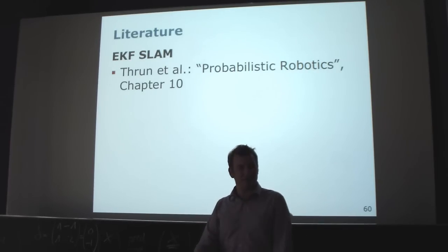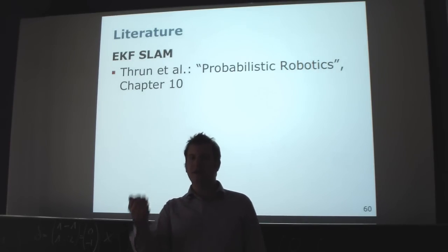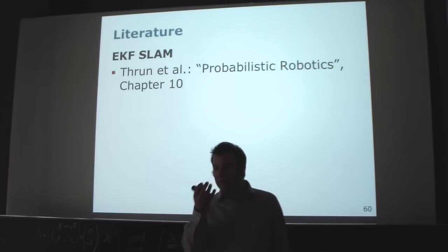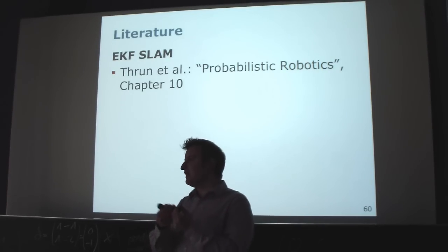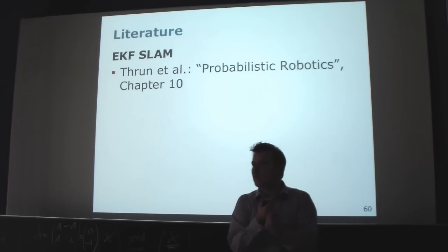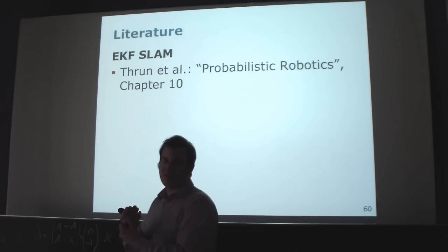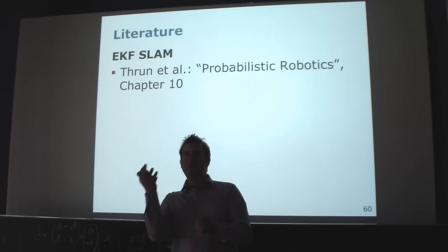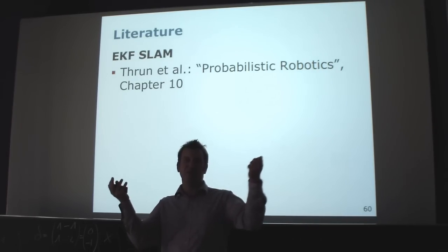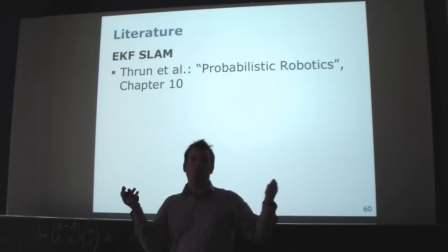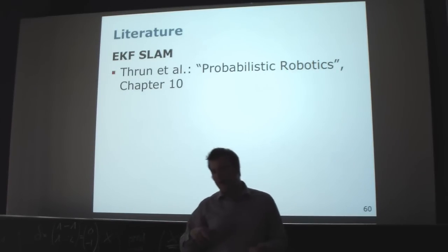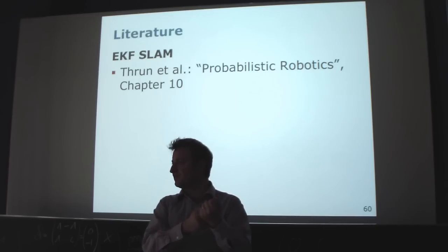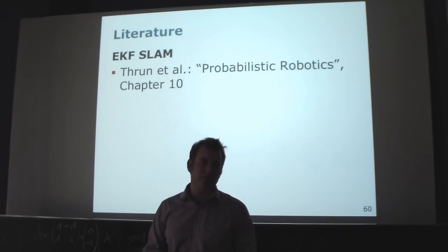So you have some gating function which tells you whether to create a new landmark or use an old one. You may create a new landmark, and later on have two landmarks at exactly the same location, which may indicate that this is actually the same landmark. But it's not that critical to establish a new landmark, although in reality this was just a single one. More critical is the other way around: saying this observation equals this landmark, although this is not the case. This is typically more critical for your system.